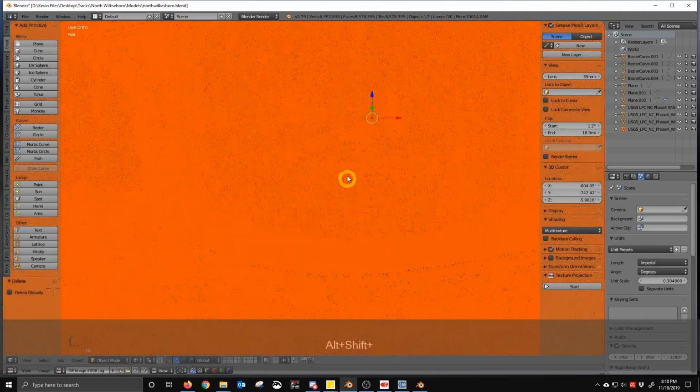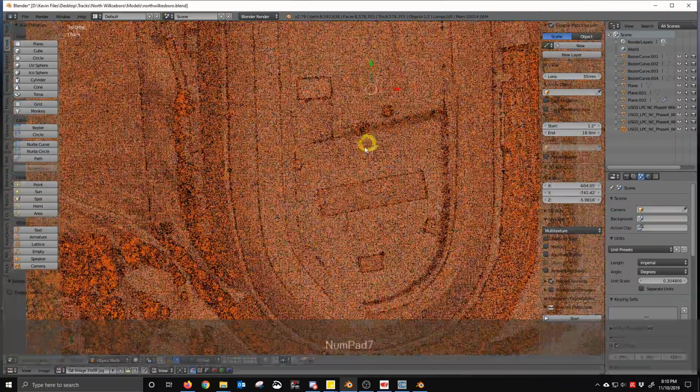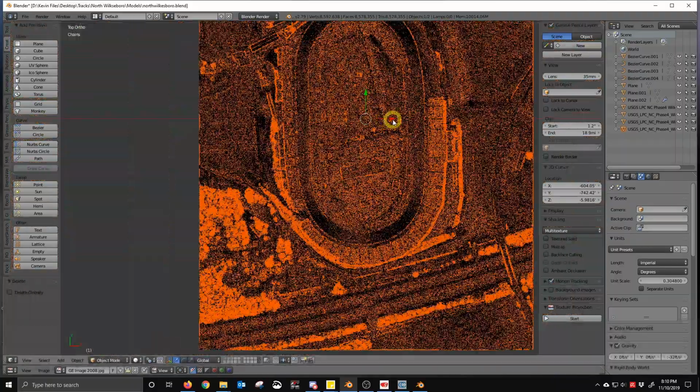You just go to File, Import, PLY format. It's pretty straightforward. I may even go over it again later, I'm not sure, in one of the next sections, but you can see everything matches perfectly between the point cloud and the mesh. There's no scale issues, so it's just a cheap little step you have to do to overcome a little bug that I found with FBX import. If you use an STL file and don't care about vertex colors, you stick with the STL format, then you have no scaling issues whatsoever inside Blender.